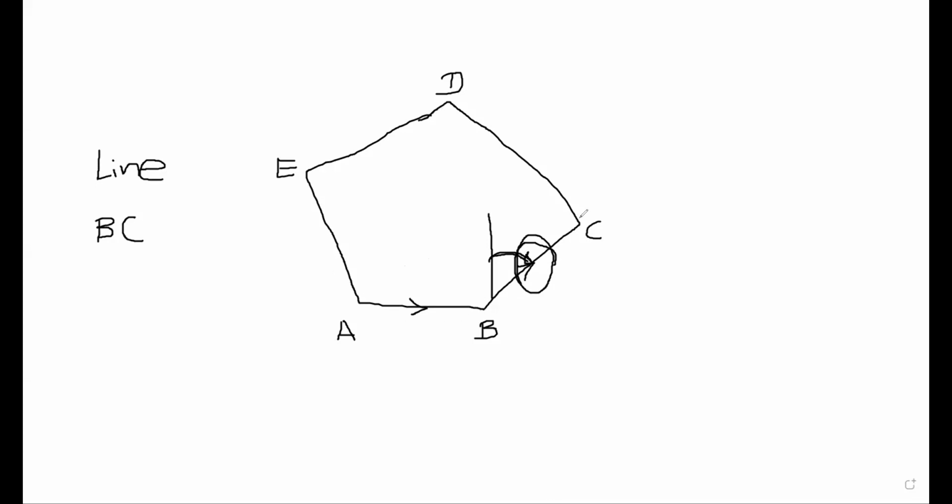So how do you move? After a line, you come to a station. Station means this node, then line. After this line, you come to this node. Then this line and this node. So along your movement, you move from line to a point and point to a line. So line, point, or line, station, likewise you are moving. Right? So you have to fill your traverse sheet in that order.